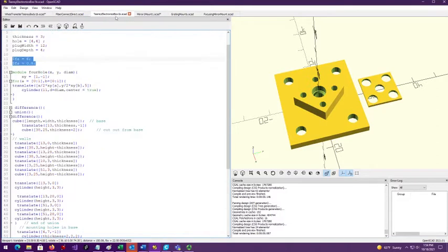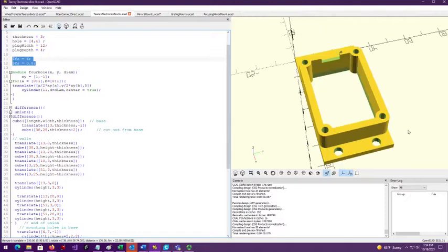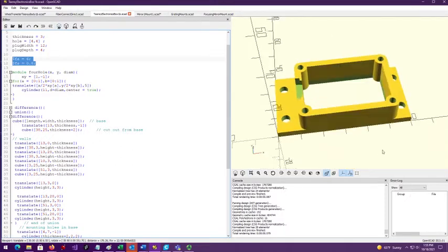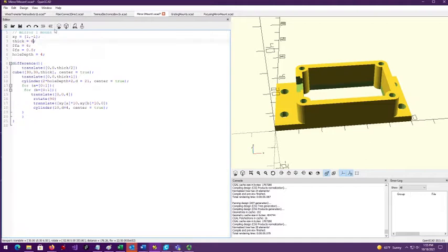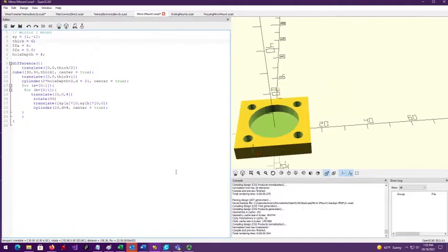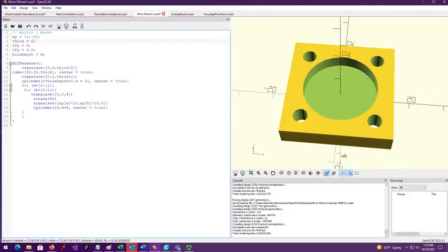Let's see what we have next here. It says Teensy Electronics Box, and this is the electronics box that fits the spectrometer to put Teensy-based electronics on this. Over here we have the mirror mount. Okay, this is mirror mount number 1. There are 2 mirrors, so you have to have 2 different mounts. This is for the collimating mirror, and it's a 20 millimeter diameter, 100 millimeter focal length spherical mirror.